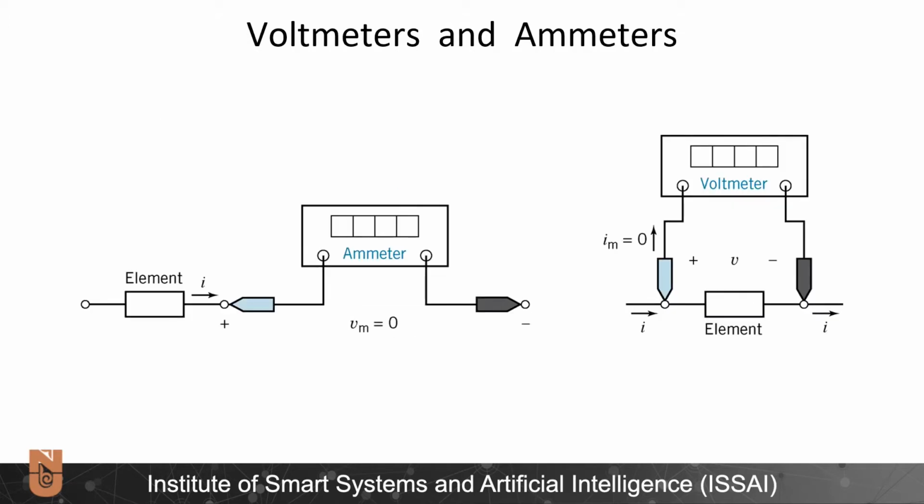In order to analyze electrical circuits in real world, we do lots of measurements. Specifically, we measure voltages and currents. In order to measure currents, we are using the ammeter. We are putting the ammeter in series with the circuit element such that the same amount of current passes through this ammeter as well, and the ammeter measures this current.